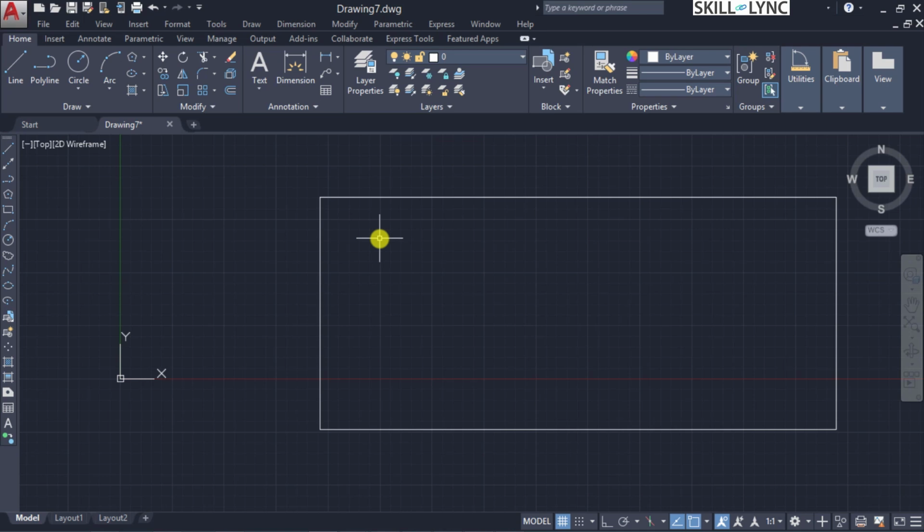If this material is subject to stress, the stress energy will get accumulated there and it's prone to failure initially. So most of the designs that we manufacture have to avoid all sharp edges at all costs, for these two causes, that is, for preventing any safety concerns and also to improve the structural strength of the material.